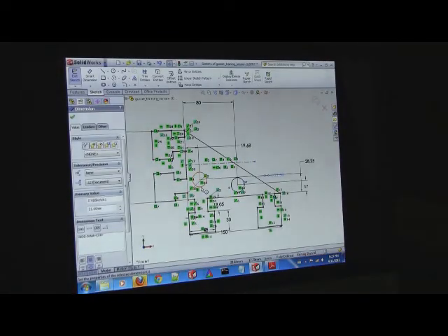Just a quick aside. You know how I told you to select all the solid lines you want to mirror and the dash line and then hit mirror? If you select more than one dashed line, it will barf. It'll ask you which one of these dashed lines is mirrored. You can only mirror about a dashed line in Sketch, so that's fine. The other way is to only select the solid lines you want to mirror, then press mirror, and it will have a little spot where it says what we are mirroring about. Put your mouse in there, select the axis, and then you're done.